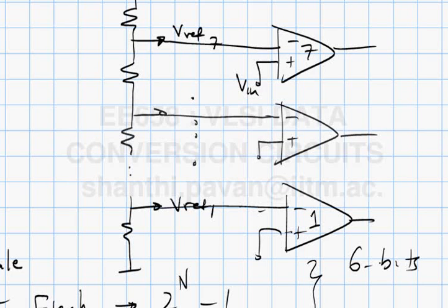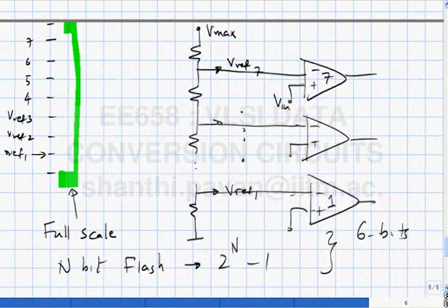If you want 6 bits and you want it now, a flash is the only idea. Thankfully, in most practical systems which require this kind of speed, 6 bits is adequate. If you rummage through the journals, you'll find any number of 6-bit flash converters. You'll never find a 10-bit flash converter, because it becomes very, very inefficient for both power and area.